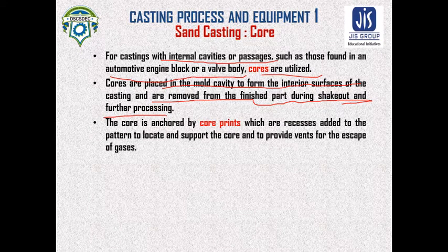The core is anchored using the core print. The core is anchored by core print, with the recess added to the pattern to support the core, and to provide vent for escaping of gases. These are the functions of core print.